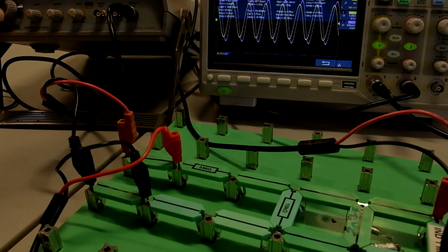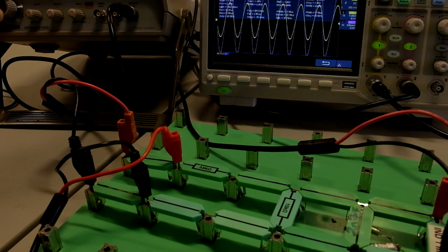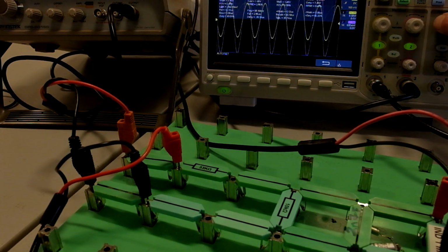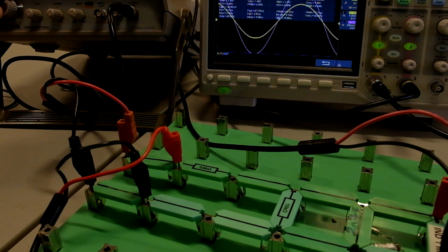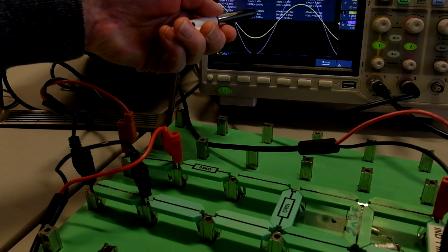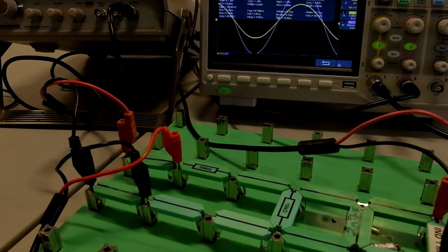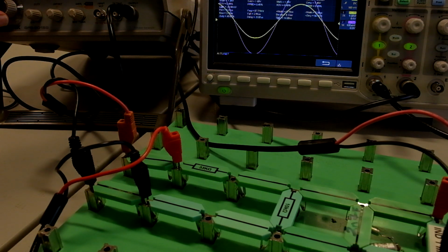So if we go down to resonance, where the sine waves in and out are completely in phase, we can measure it. Turn the time base down a little bit to get it as accurate as possible, tweak the frequency going in where they cross the zero axis, and what we can see there, yep, that's good. We can see reading off here 97.7 kilohertz, which matches the theory that we previously predicted.